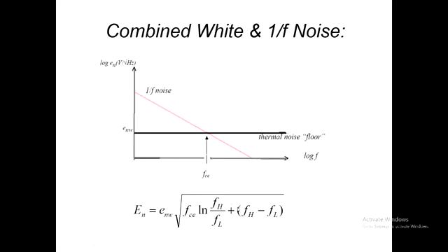Alright, so if we're looking at a low frequency process where the 1 on F part is prevalent, then we could set FL here and FH here, and then we just have to work out the area under this trapezoid to characterise the amount of noise present, because the white noise is logarithmically that far below that we can just ignore it, yeah? Alright, now, the problem can be when we're straddling those 2 points.